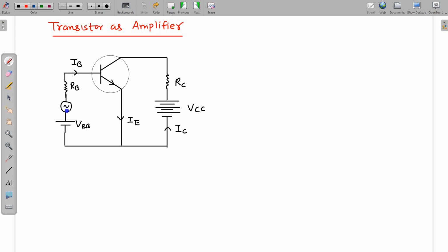For example, when we use a mic and say something, our voice enters the mic as a voltage signal, and that fluctuates the voltage of this input circuit. VBB and VC are just for proper biasing of the circuits, and this alternating voltage shown here is just a symbolic representation of signals.